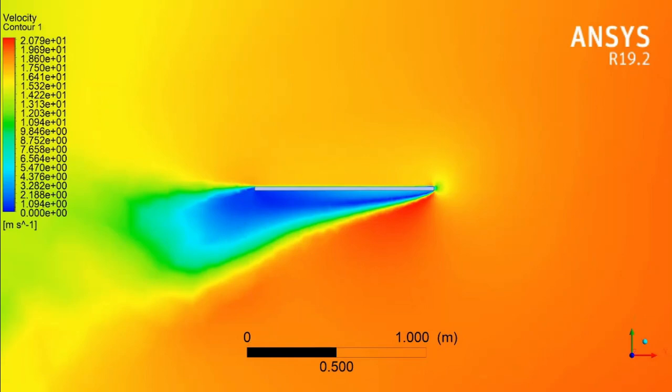This velocity contour is a method of measuring stream discharge, in which point velocity measurements are translated into average cross-sectional flow velocities. By considering the point velocities, these averages are then multiplied by the areas of the cross-section to give the discharge.